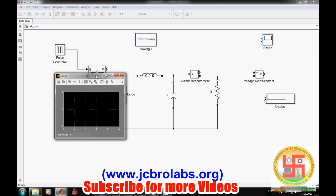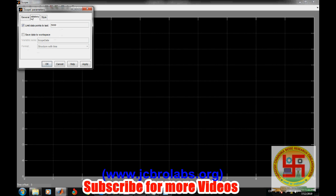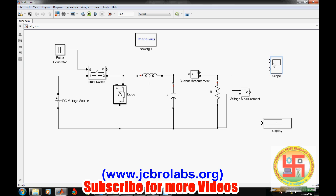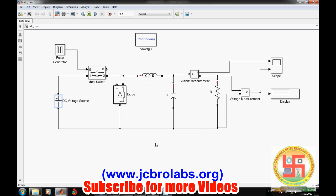Let's configure the scope. We need 2 current and voltage measurements, so we need 2 axes, and in history we unlimit this. Apply, and then okay. We will be measuring the current and voltage. One is connected to this, and another is connected to the current, and here we will be measuring the voltage on display. Change the DC voltage source. We need 30 volt. Okay, let's save it. It seems like everything is fine.